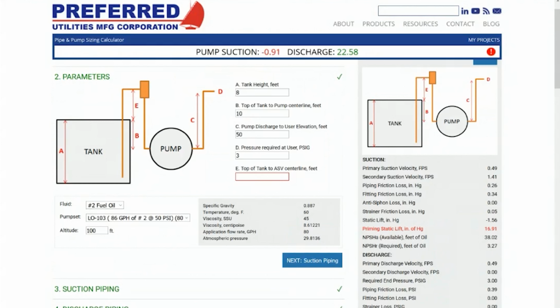So you may have a situation where if that value is very large, if everything's perfectly primed, it's going to run fine. But on startup and commissioning, if there's not a way to manually prime that, it may not actually be able to pull that fuel up and over in a dry system. Keeping in mind that with a positive displacement pump set like this, if the pumps are bone dry, they're not going to be pulling air quite as efficiently as they would pull fuel with those internals wetted by the fuel itself.